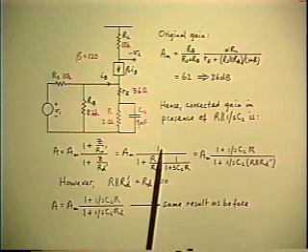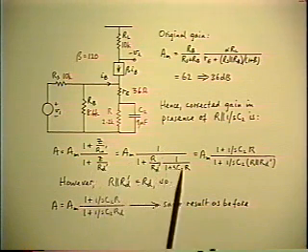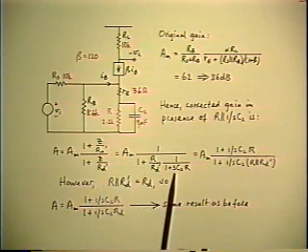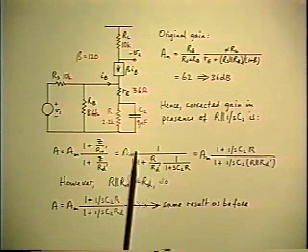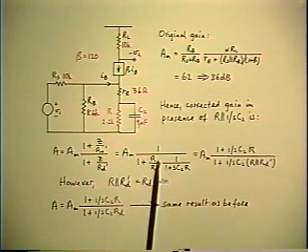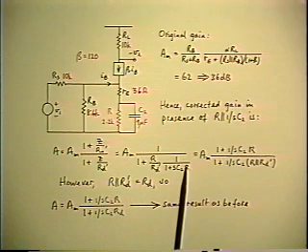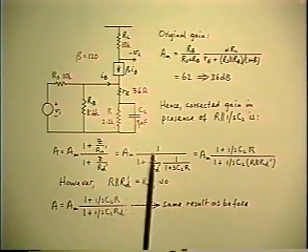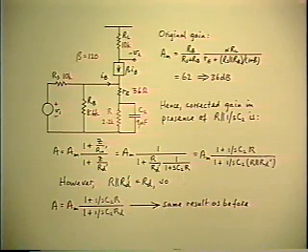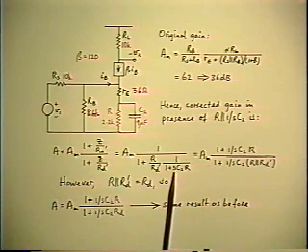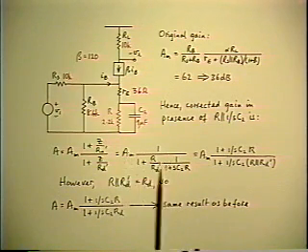So the numerator is 1, and in the denominator you have a little more complicated combination for the Z now. Now it's the parallel combination R together with a single pole caused by the time constant of the R and the C2. So this time you've got one more line of algebra to do to get the final answer